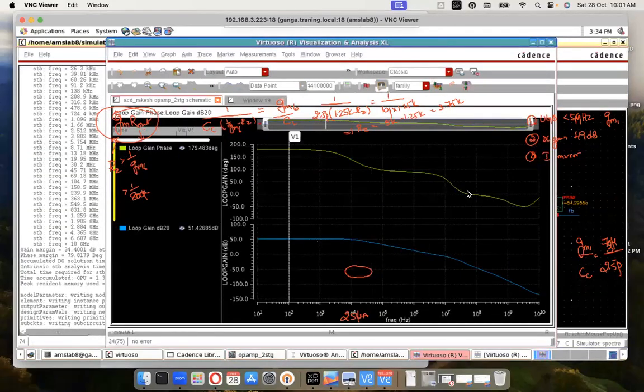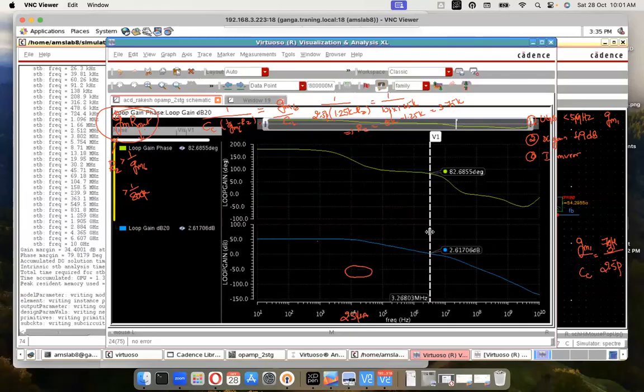Okay. The phase somehow looks like it is trying to move up, but there's an immediate pole coming into the picture. Where is this pole coming from now? It could be from anywhere, even a parasitic pole, but it is at a very high frequency, so we may be able to ignore it. Your UGB has improved.